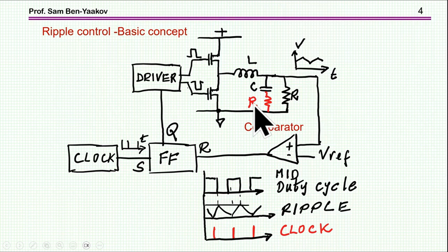It is not just a parasitic element, but it's really important because the ripple that we see here, the triangular waveform, is in fact due to this resistance. Okay? So it is inherent in this design of the control that you need this resistance. We'll see later on that you can get by without it, but the basic idea actually relies on this resistance.